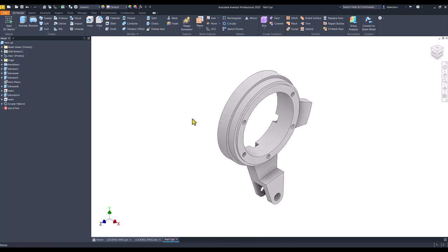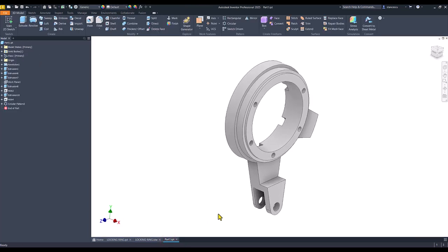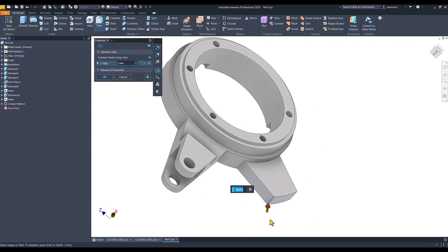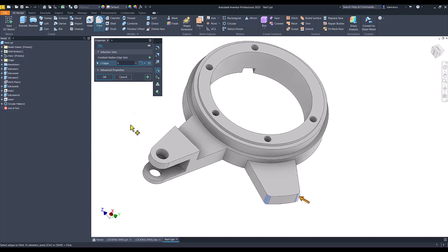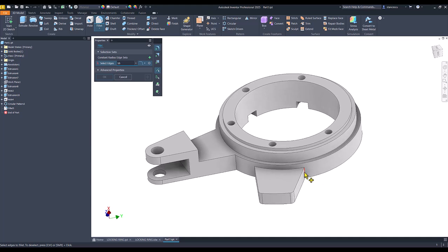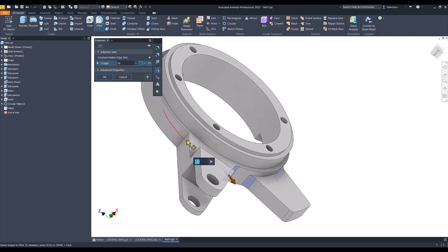feature or cut. The part has some fillets. You see radius 5 these two and radius 10 1, 2, 3, 4. Let's apply. I select firstly this edge for 5, then plus 10 to 1, 2, 3, 4. Okay.